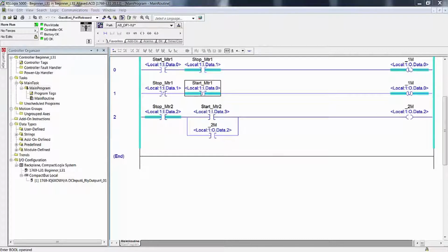There are also 4 photo eyes labeled 1 PE, 2 PE, 3 PE, 4 PE. These happen to be reflective. It shows a reflector on the opposite side of the conveyor from the box marked as the photo eye. This type of photo eye has a transmitter and a receiver, and it's designed in such a way that extraneous light does not affect it.